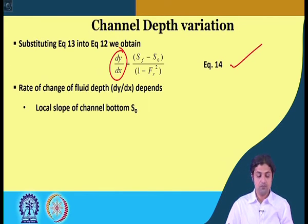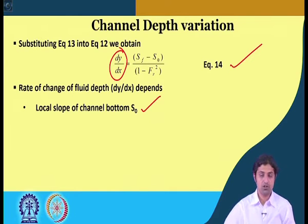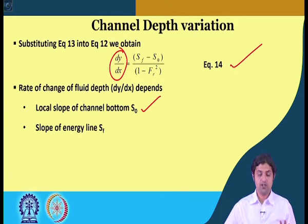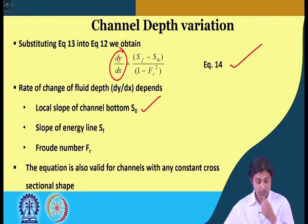This dy by dx depends upon the local slope of the channel bottom, which is called S naught. It also depends upon the slope of energy line SF, and it also depends upon the Froude number Fr.